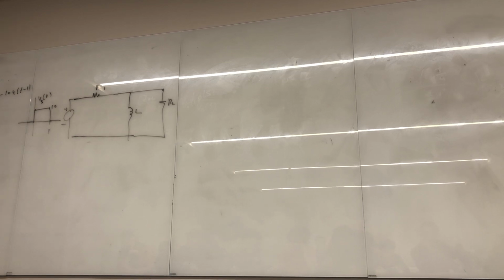Now when you take the transform of this, what happens? Vs of s becomes what? Well, the first one is just 10 over s, right? What about the second one, time delay? What happens? Minus 10 times what? It's over s, but then I have a phase of e to the minus s here, don't I, class? Do you all agree with me? How many understand that? Whenever you have a time delay, it brings in a phase right there.